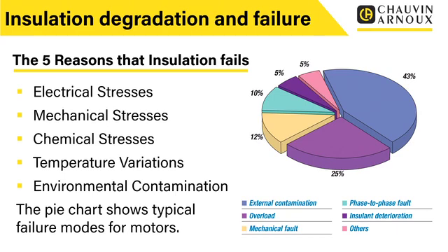Mechanical stresses. Mechanical stresses are to do with starting up and shutting down. That could put torsional stress and things like that, mechanical stress within the windings and within the insulation. Also, balancing issues can cause a lot of mechanical stresses. You can imagine that if it's vibrating or if the machine isn't aligned correctly, these again can cause mechanical stresses on the insulation. Chemical stresses, again, come in many forms, but this could be the proximity of chemicals, oils, or maybe even corrosive vapours, dust. All of these things can deteriorate insulation.